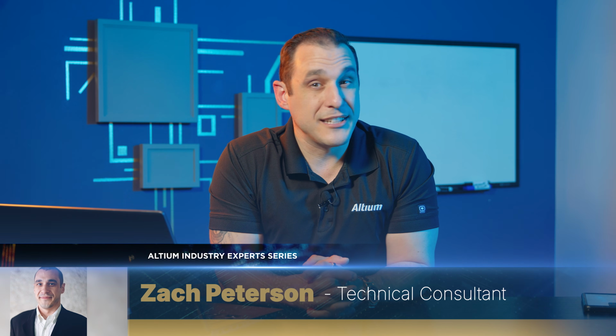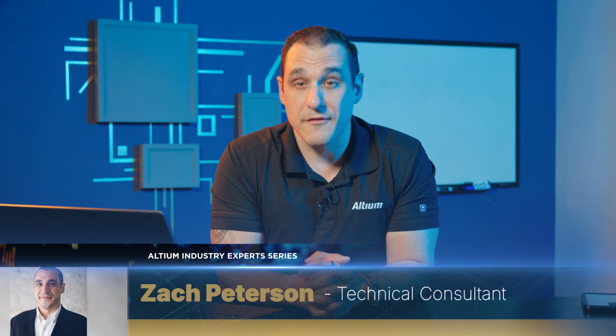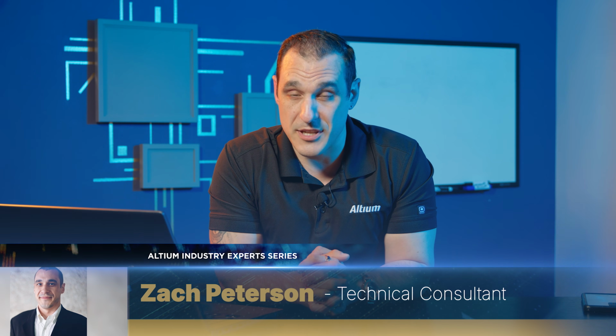Today we're going to be doing a little follow-up video to our recent video about decoupling capacitor placement and why it is less important when you're using planes versus using traces. Now this follow-up video was all spawned by a message I received from a viewer through LinkedIn. And this message specifically concerns the use of traces versus vias to make connections to power and ground nets when placing and connecting decoupling capacitors to integrated circuits.